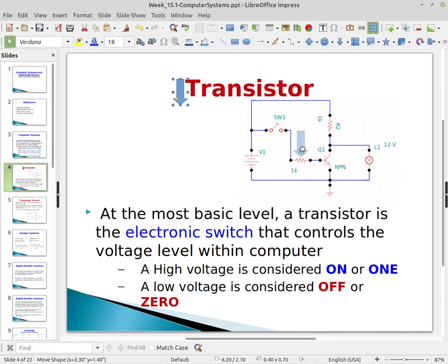So what happens is when this switch is closed, you get a high voltage on this circuit, so you get current flowing down through this circuit into this transistor, and you see that arrow there. And the current is going to be flowing in the direction of that arrow. So current flows through this and turns this transistor on. When this transistor here, Q1, turns on, what that means is that the voltage between the 2 points right here goes to a 0. Okay, so this type of circuit is actually an inverting circuit.